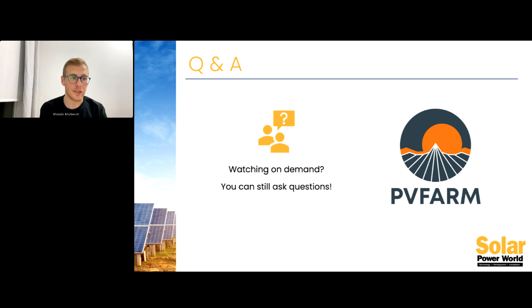In that terms, I would still say that the most accurate way of answering this is to have equipment chosen, or at least you need to have an idea what trackers you're going to use. Because when we analyze slopes, it's basically slope per 1 unit of length, per 1 foot, right? But then on the site, we're going to use a tracker of 300 feet. And if it's terrain following, it's going to go serpentine within a certain restriction. So it's not entirely different, but there are two different analyses, and we would recommend to go through both.